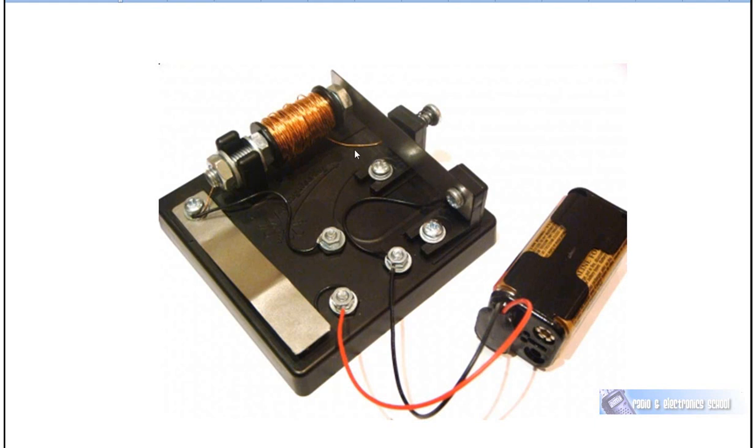The circuit is this wire here going underneath the armature to this screw, and that screw is just touching that movable armature. Let's have a look at how current would flow through this circuit. Electrons would leave the negative terminal of the battery, and they would travel this way through the wire to the armature. And remember, that bolt is touching the armature, so the electrons travel to the adjusting bolt, then through this wire, through the electromagnet.